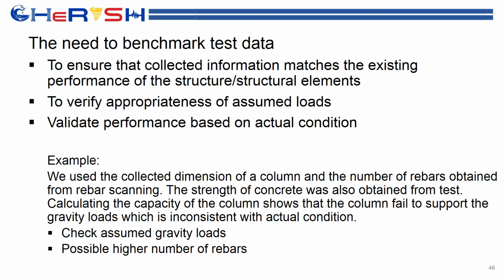We also need to verify the appropriateness of the assumed loads and to validate the performance based on actual condition. Because, for example, if we use the collected dimension of a column and the number of rebars obtained from rebar scanning, plus the strength of the concrete that was obtained from the test,